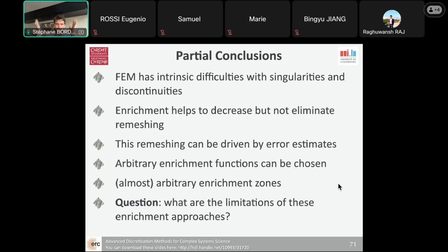But what you need to know is that the method we use is called linear elastic fracture mechanics, LEFM. That assumes that the cracks are already there. That is a theory by Griffith, which is really 100 years old. It always assumed that you knew where the crack was, and your question was, how long will that structure last? And you just assume the worst case scenario. So the crack exists, and it's related to the debonding between atomic planes.